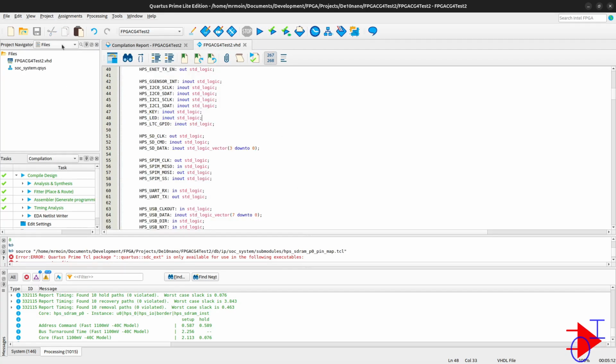Obviously, remember, for this to be correct, you want to be sure that your project is configured for the correct device. So if you are using DE10-Nano, using this instruction, make sure that it is this. And the best way to check this for your particular card is to make sure that the device number written on your Cyclone chip matches the device configuration of your project.